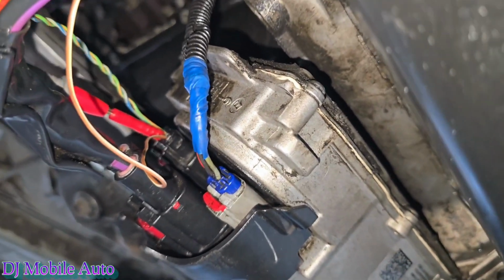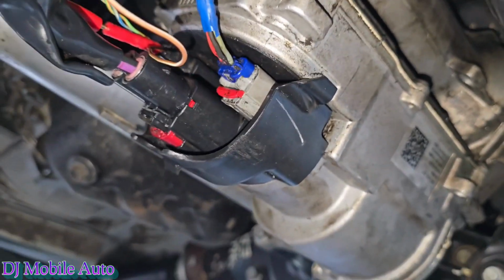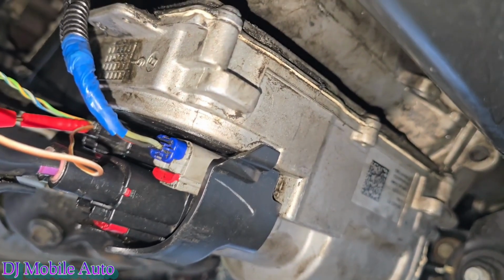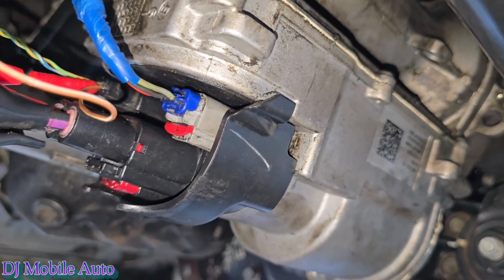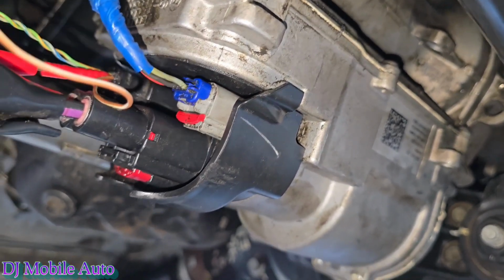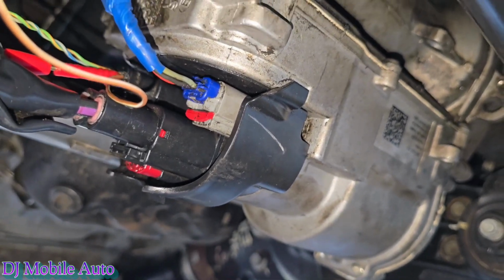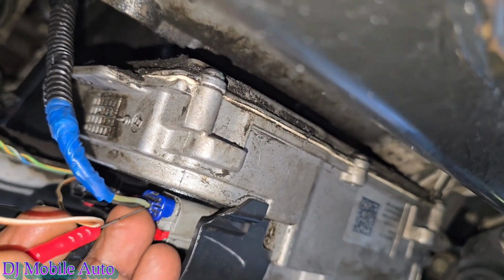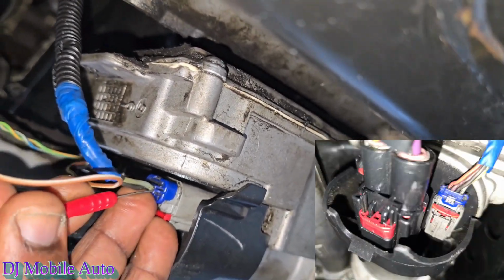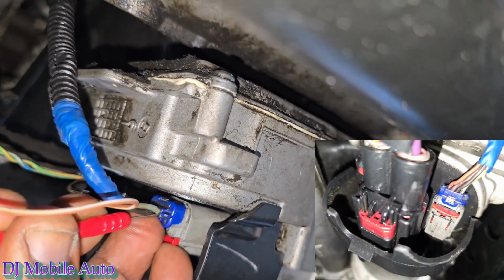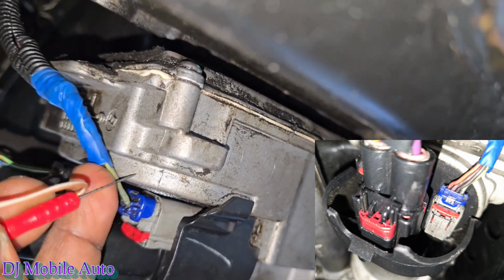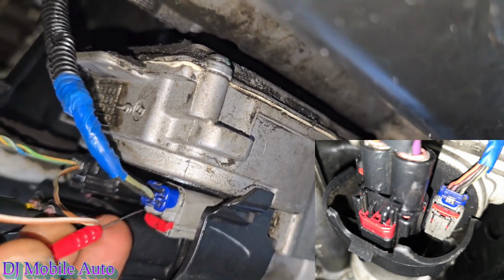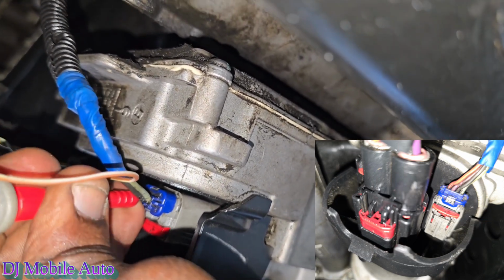My harness coming to my motor is good, and this one is for the, what you call it, torque sensor, just going into the rack itself, right? But I don't think I gotta pay attention to that because the fault code is for the control module and not the torque sensors. But I mean, it won't hurt to try to see what's on each pin. Okay, so on this green wire here, I'm getting 2.8 volts. Okay, so I'm not sure what that is. On this black wire, it might be, what's that, ground. I got a purple wire right here. Let's see what this purple wire is.